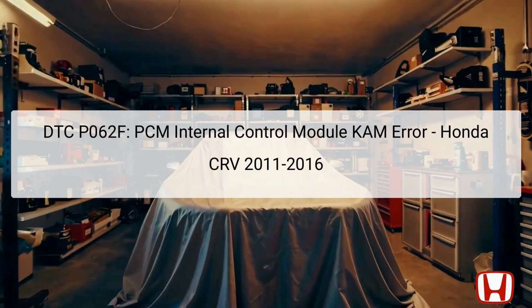The DTC P062F pertains to a malfunction within the Powertrain Control Module, or PCM, particularly related to the Keep Alive Memory, or KAM. The KAM is crucial because it stores vital information about the vehicle's operation, such as adaptive learning parameters, even when the vehicle is turned off. If the KAM experiences an error, it could lead to various performance issues as the PCM relies on this stored information to optimize engine management and fuel efficiency.